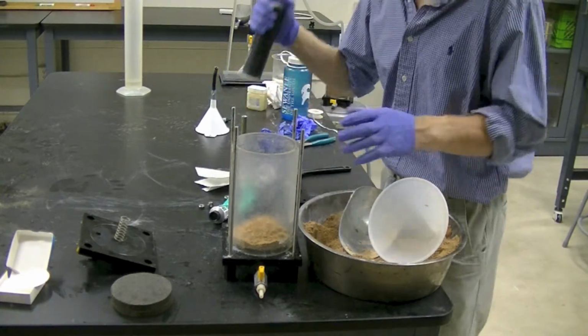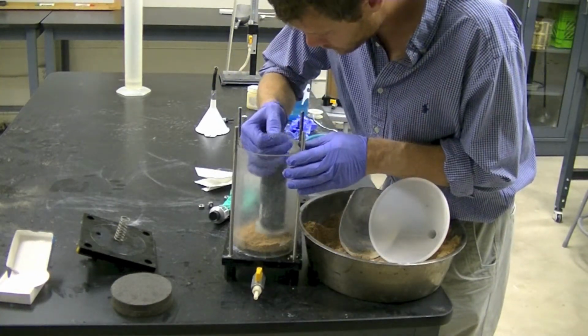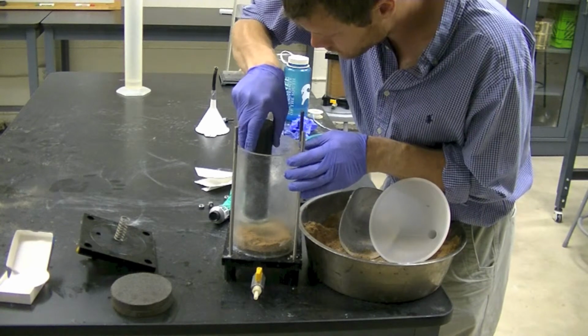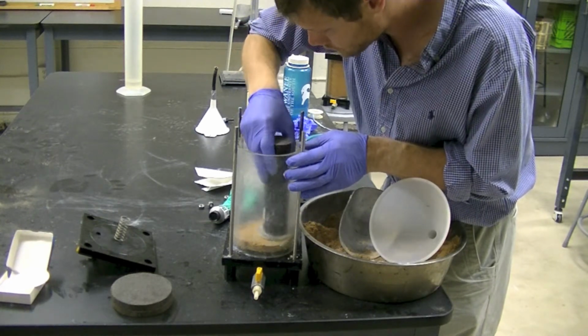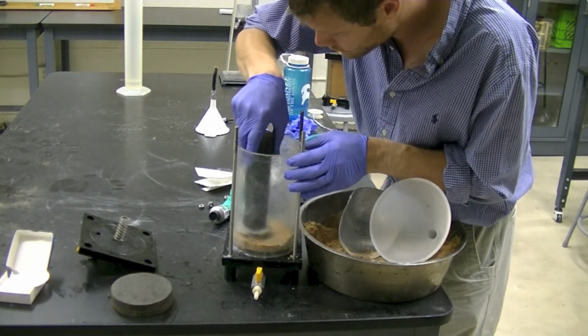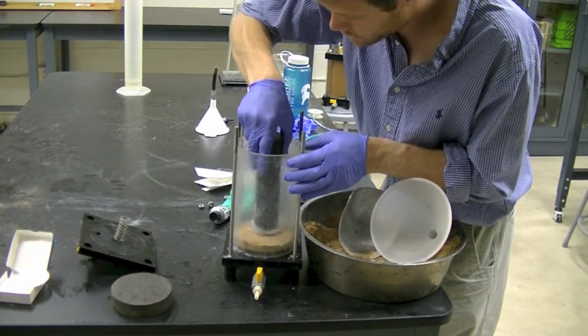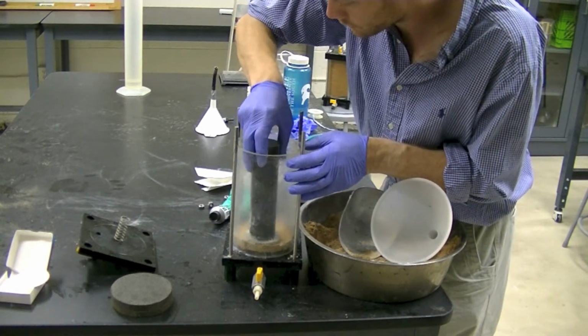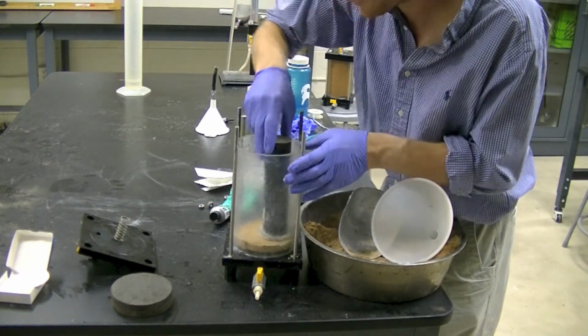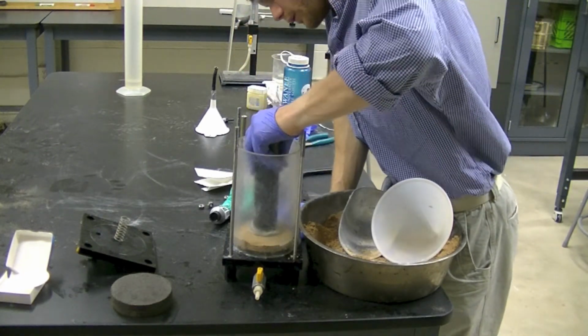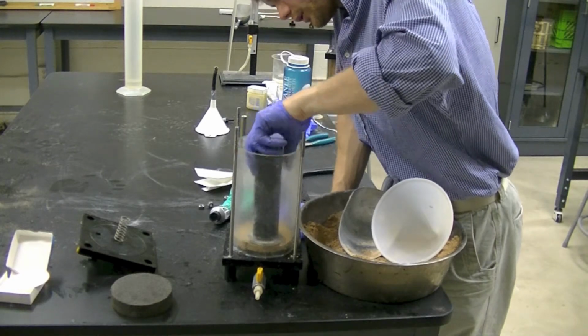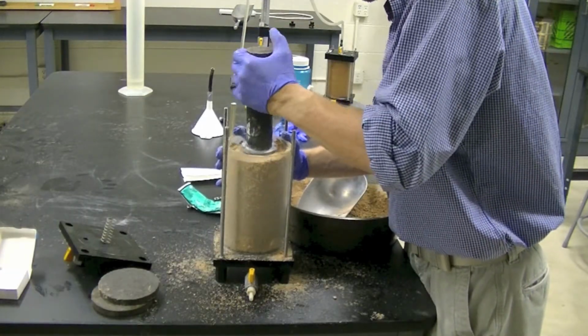Use a weight tamp to tamp the soil to the desired degree of compaction once the lift is placed. Oftentimes it will take multiple trials if a specific degree of compaction is specified. Use the same number of tamps at the same drop height for each lift. Drop the weight freely in a circular manner around the whole area of the lift. Compact each lift in the same fashion until the permeameter is full.